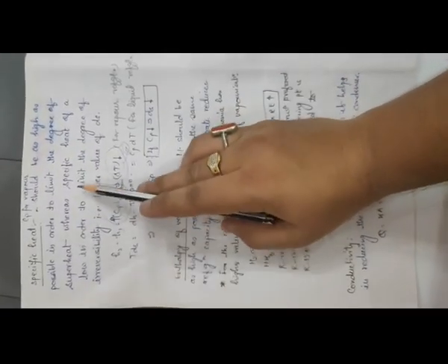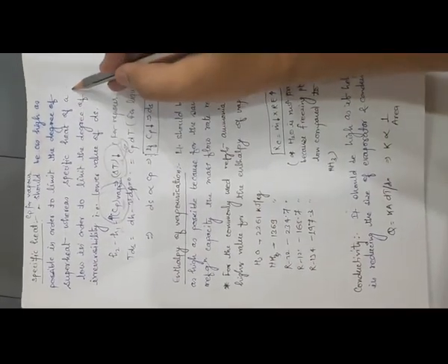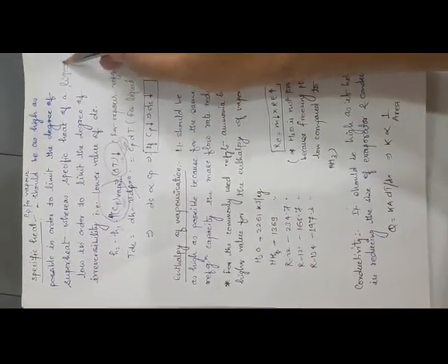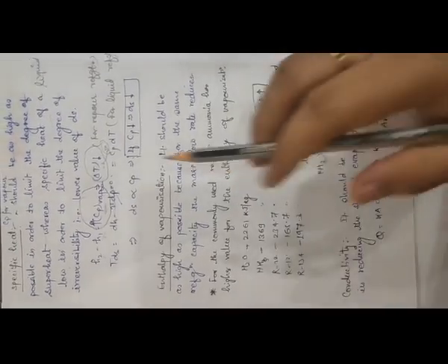Also, specific heat of a liquid refrigerant should be low in order to limit the degree of irreversibility. That is the lower value of change in entropy.